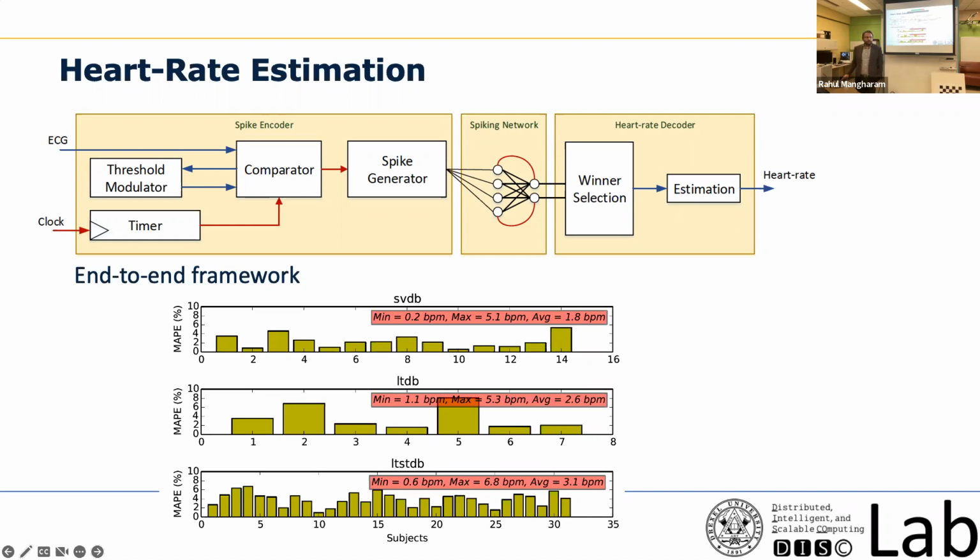I think the other thing you can mention is the 4% energy that is consumed. With the SNN, the energy consumption is extremely low. In the test we ran at that time on that Samsung watch, running the Pan-Tompkins algorithm for heart rate estimation, the battery went down completely in 1 hour. With our approach, it ran for 2-3 days without any problem.